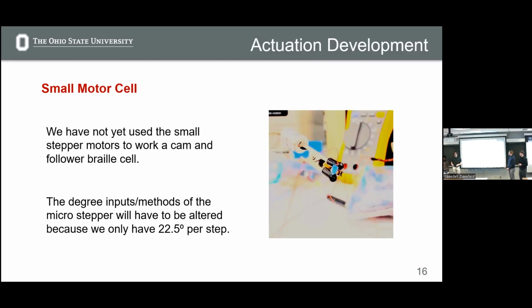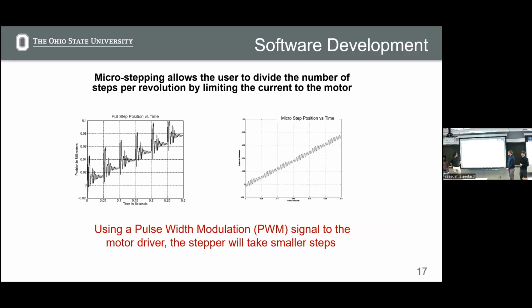And that is a lot coarser than we need for our use. Again, 22.5 degrees per step. With that 72, 72 type setup for the lower two, 3 movements would get us behind that, and 4 would get us over that. So the pins would not actuate correctly with the current setup. What can we do about it?